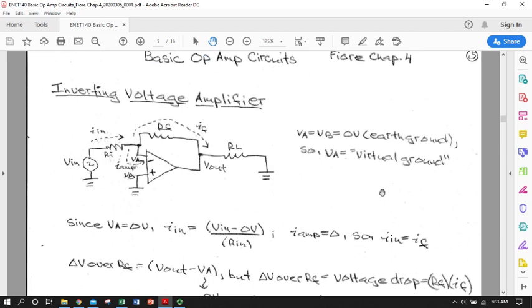Okay, we are going to stop here and pick up with another lecture for the inverting voltage amplifier. We'll probably end up with at least 3, maybe 4 individual lectures here for chapter 4. It's a fairly big chapter, but for the derivation of your gain equation, where we use the feedback network, you'll probably notice that we were, whether formally or informally, using Kirchhoff's voltage law and Kirchhoff's current law to derive our gain equation. And we can either use that equation or just look at the circuit sometimes and do a little KVL in our heads and get the gain, or do both and be really sure.